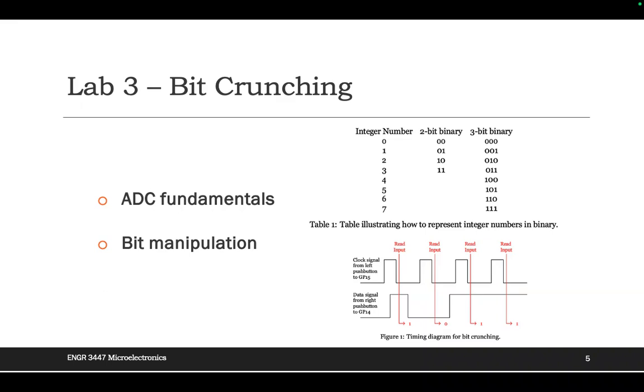One is for the clock, the other for the data read. The clock means every time I press it and release it, I read the data. And for the read data, if I press it, it means 1; if I didn't press it, it means 0. Which means I can read any number of bits I want, not only 1 bit, 2 bits, or 3 bits. I can read as many bits as I can. Does that make sense to you?